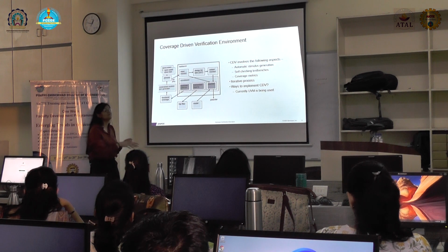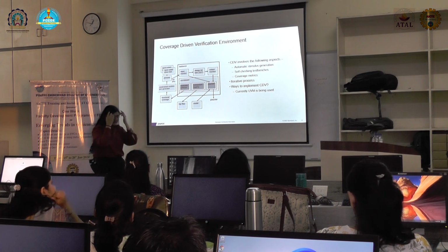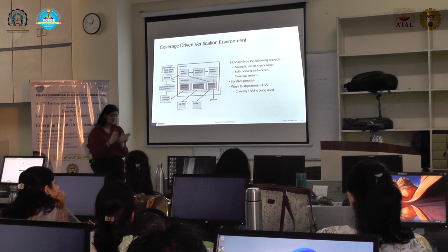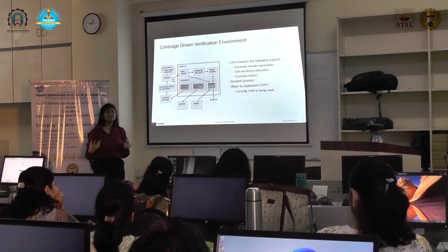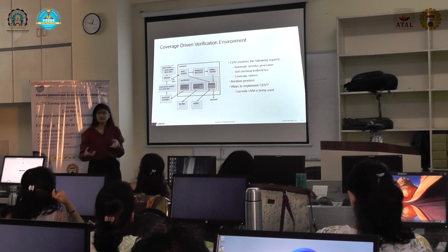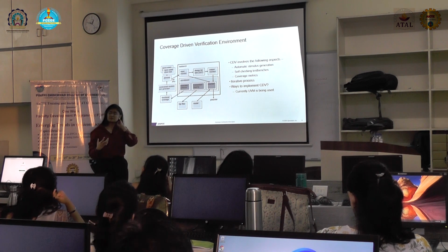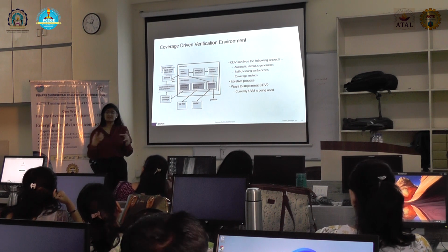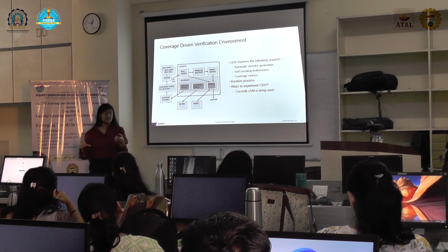So moving from the Verilog testbench to the constraint-driven testbench, there is a huge difference. First, we are moving from Verilog to SystemVerilog. SystemVerilog involves dynamic structures of classes, and object-oriented concepts are there. What object-oriented concepts do is share data across different objects.